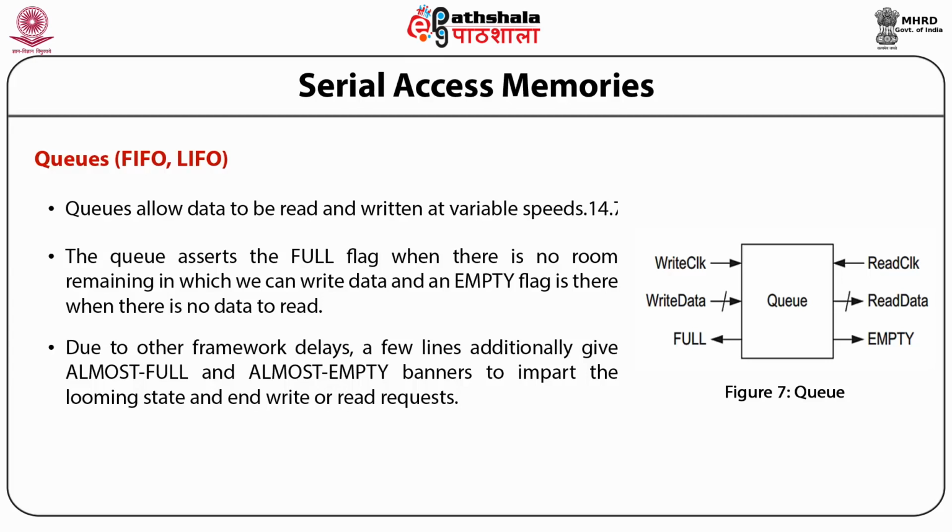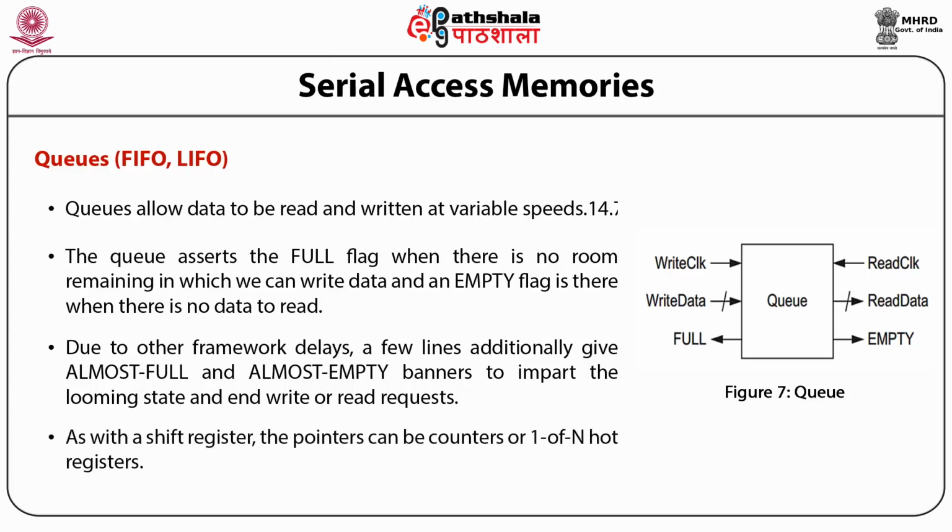The queue inside keeps the read and the write pointers, showing which information should be accessed next. So as with the shift register, the pointers can be counters or one-of-N hot registers.